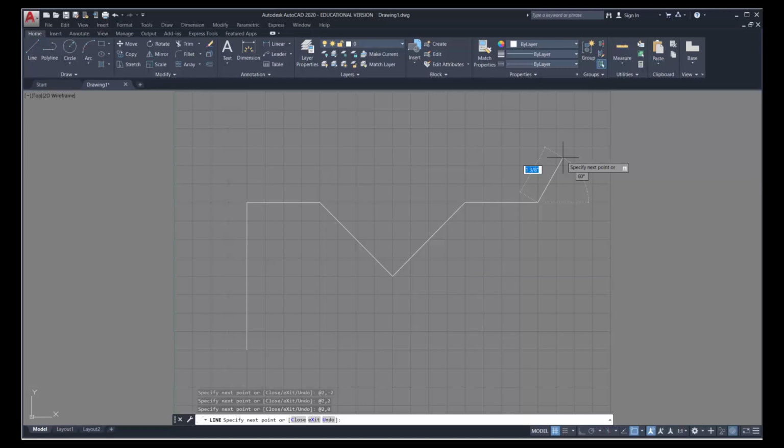Now going straight down 4, again, I'm looking at my drawing. Notice how it's indicating as 0, -4. Once again, we're not moving along x. We're simply moving down along the y position. And here, I can type in -8, 0.